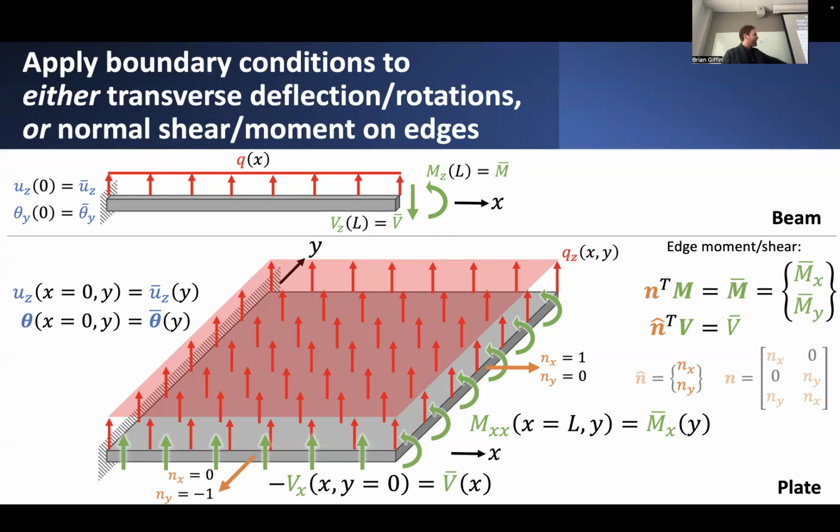But again, in profile, if you were to look edge on at the beam or the plate deflecting under whatever these transverse loads are, it wouldn't look so different in some ways to the bending of a beam. So at the end of the day, beams and plates, not so different. It just means that you have much more complicated solutions. And usually you don't go about solving these plate bending problems by applying classical analytical solution procedures. Usually you would use some kind of analysis tool, finite element method, to discretize the plate into corresponding plate or shell elements to represent how they would deform under the load.